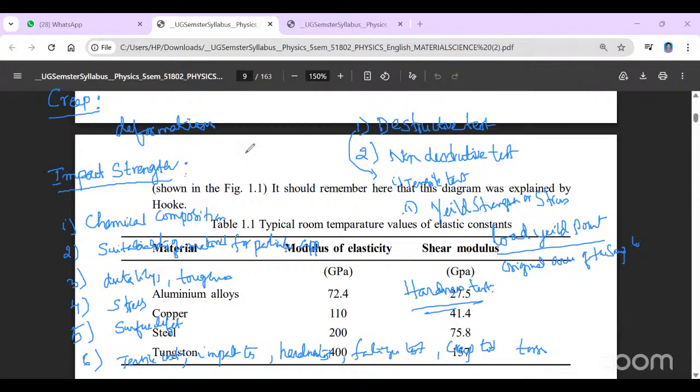the flattening of the steel ball is eliminated. In the Vickers hardness test, we have a formula to measure the hardness of the material. That is the load applied in kilograms divided by the area of indentation, which gives kilograms per millimeter square units. Okay, so these are some of the different tests we have. Next, we'll move to the modes of fracture. Under the modes of fracture, we have ductile fracture as well as brittle fracture.